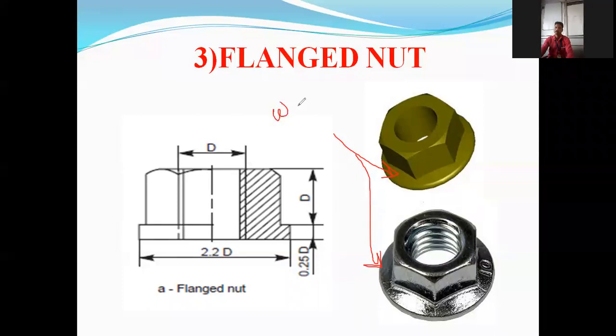What is a washer? In Marathi we say "vaysar", but the correct technical name is washer. Whenever we are using this nut and bolt arrangement, what is the main function of the washer? Tight fitting. But how? It helps us to increase the contact area.